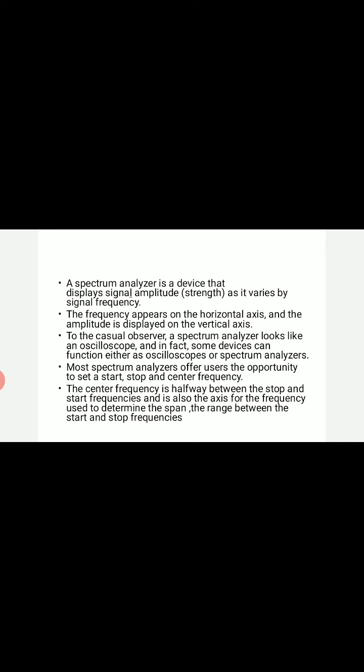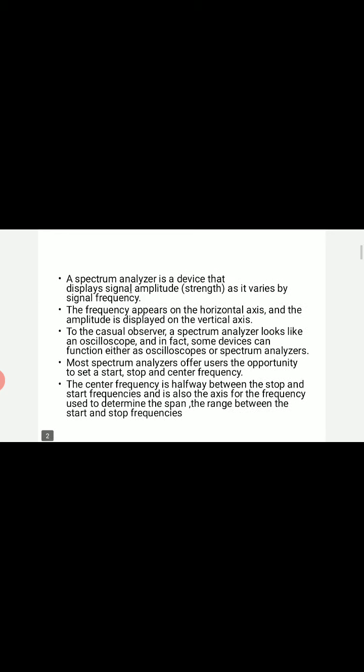Most spectrum analyzers offer the opportunity to set a start, stop, and center frequency. Center frequency is halfway between the stop and start frequencies and is also the axis for the frequency used to determine the span, or the range between the start and stop frequencies.